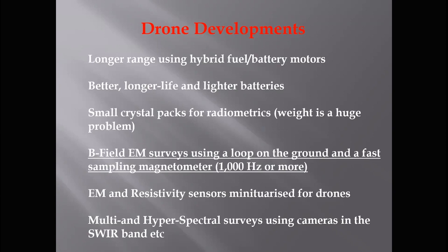So you have to have a massive investment in batteries and be charging all the time and bringing the drone back to base after every half an hour, put new batteries in, take off you go. So then your issue is, can we use a hybrid fuel? Can we use fuel? Or can we use a hybrid which is using fuel and batteries? Problem with that is we have even more issues with fuel because governments fear that when the drone crashes, the fuel is going to explode and you're going to start a fire. And if that's in an urban area, then you have massive problems.